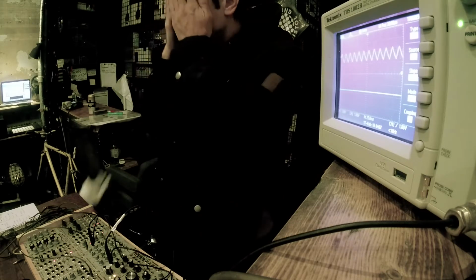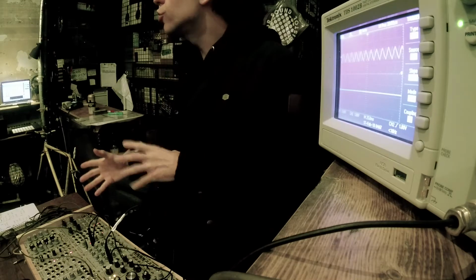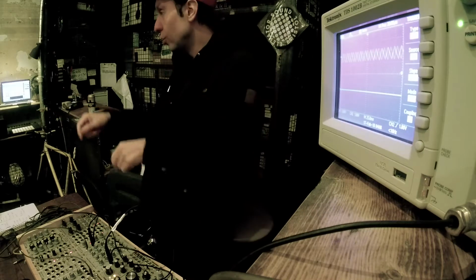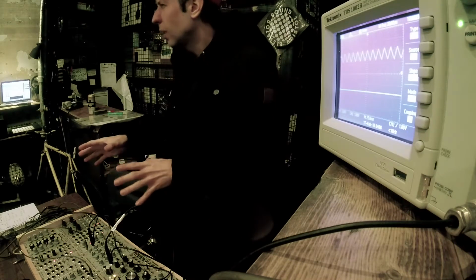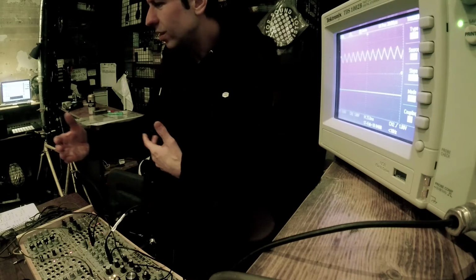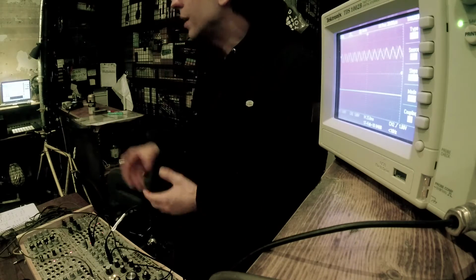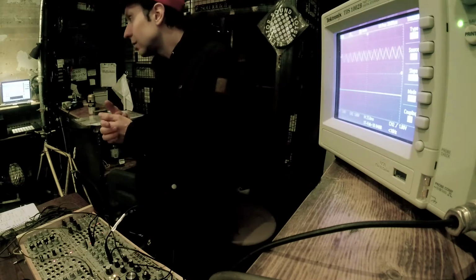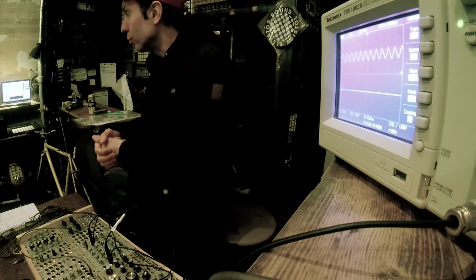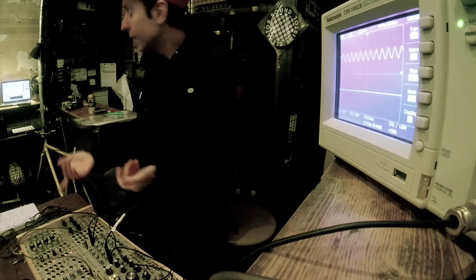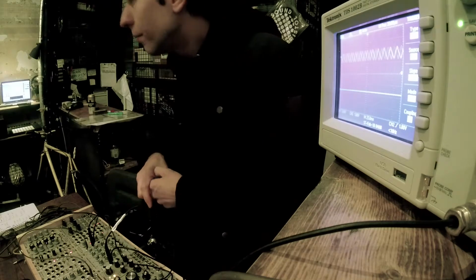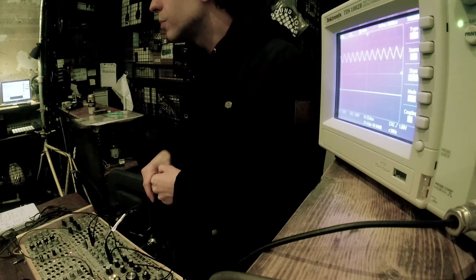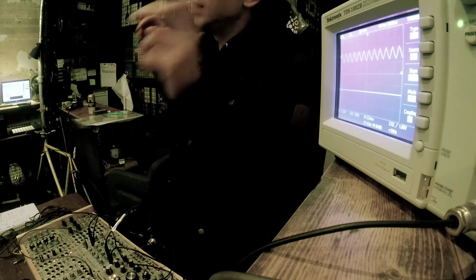It normally comes forth really obviously if you have a mixture of acoustic instruments and synthesized things. Then you understand, when you mix a gig like this, wait a minute, why does the electronics not blend? It doesn't have the depth, it just doesn't work. But if you make sure that in your electronic sound sources the intensity is linked to timbre and amplitude, then you lose this problem. And that's why the low-pass gate is good. That's a really important aspect of creating a kind of acoustic-y electronic sound.